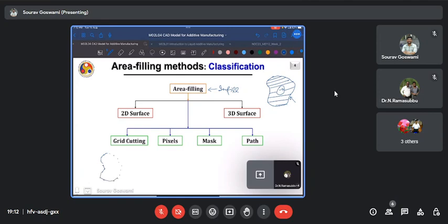Now, for an STL file, we know that the representation is approximate, and so even linear interpolation is sufficient for joining these dots. However, if you are performing a direct slicing, which captures the geometry more accurately, then some other forms of interpolation might be needed.